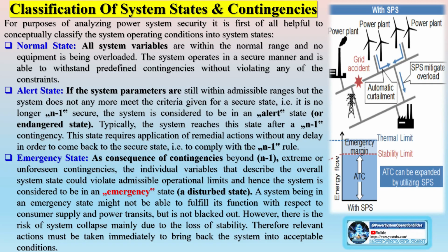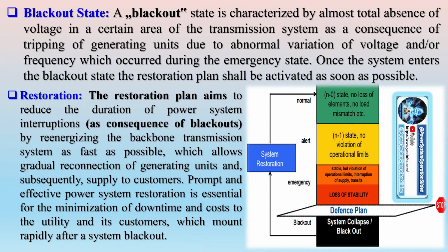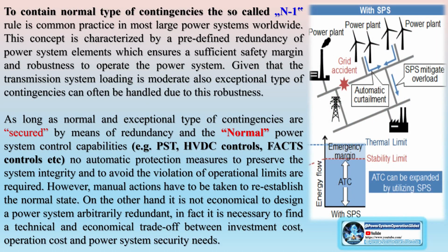Frequency instability occurs when power system frequency varies beyond the operating limits. Corrective actions include generator tripping, rapid generation reduction through fast valving or water diversion, control of HVDC power transfer, load shedding, controlled opening of interconnection to neighboring systems to prevent spreading of disturbance, controlled islanding of the local system into separate areas with matching generation and load, etc.